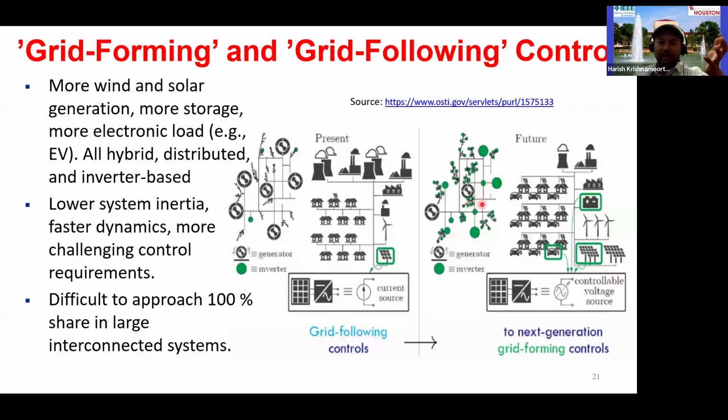The inverters are predominantly made with power electronics, so that's why again power electronics is becoming very important going forward. The problem with power converters is that, compared to a rotating machine which has the inertia of the machine itself, power electronics are just semiconductors which react very fast. So that inherent inertia in the grid is missing. What that means is maintaining the grid frequency, controllability and stability is slowly becoming a challenge as we go more towards a power converter based future. But then there are a lot of flexibilities that power converters can give.